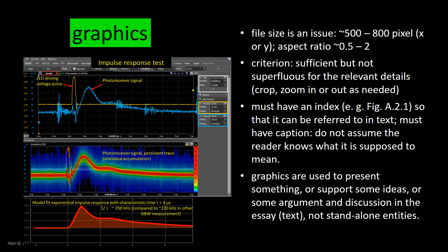For the scary-looking figure on the left, it is a time domain test of an LED photo receiver system. A 250 nanosecond pulse, the yellow spike, is sent to the system. But the best the system could do, as shown with the blue-red trace, was to gradually rise, which took almost a microsecond, and even more slowly fall over several microseconds.